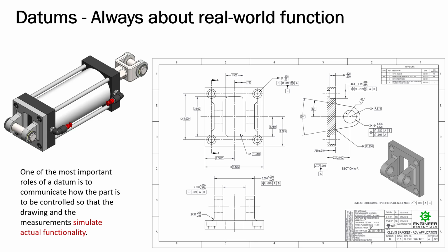So here it goes. If the GD&T is applied correctly to the drawing, and what I mean by that is that the DRF, the datum reference frame, has been established and matches the function, and the feature control frames are applied with the correct geometric tolerance and back to said DRF, it most likely will never be optimal for machining, but should be able to be inspected.